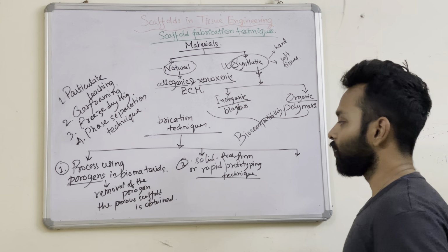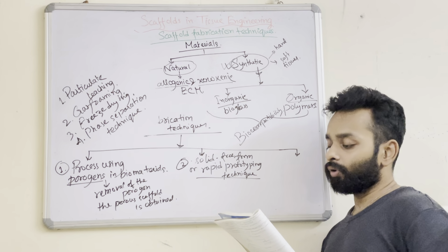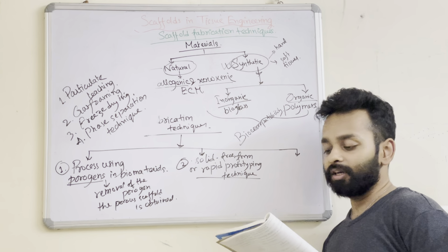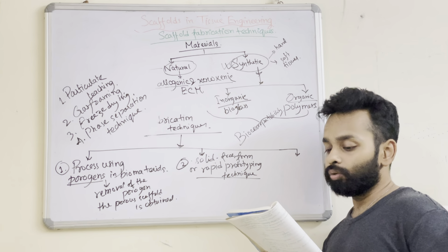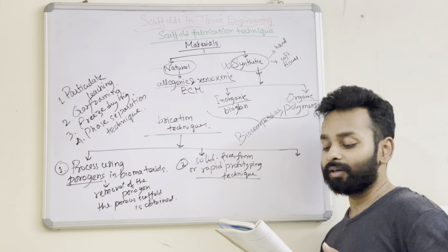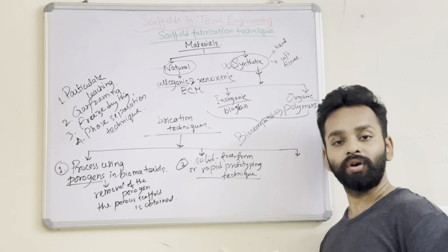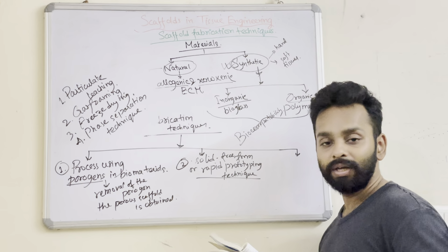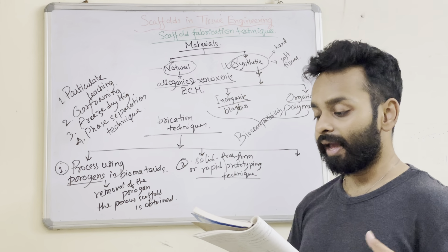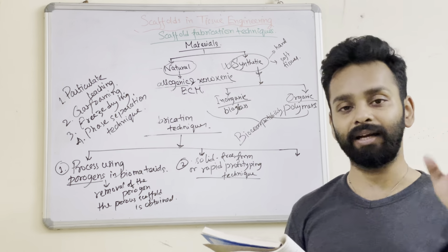So the second technique is the solid free form or rapid prototyping technique, wherein hierarchical porous structures can be manufactured by sequential delivery of material and/or energy needed to bond the material to preset points in space. So there will be a hierarchical porous structure which can be manufactured through a controlled delivery of the material or energy needed to bind the material to preset given points in space.